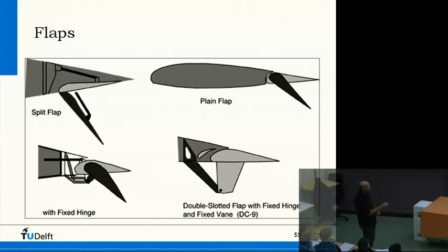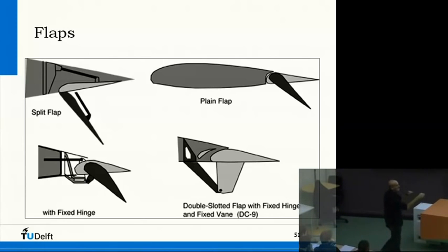And the curvature is first like this, and then like that. If you curve it more, then the extra lift vector will point upward. And if you deflect it up, then of course there is an extra lift vector downward, so then you go down.